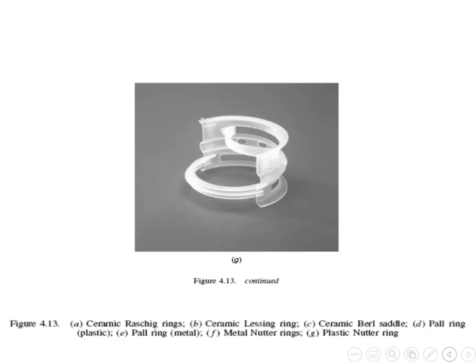And finally, I defined for you sphericity or shape factor, and I can use it whenever I have those non-homogeneous, non-spherical particles. All you have to do is replace, let us say, the effective diameter with the sphericity times the nominal or equivalent diameter.